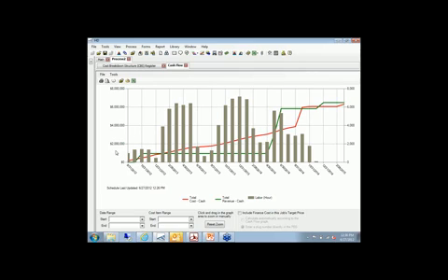And again, this is another thing where if we want to really work on leveling out these resources where we don't spike up and then have these valleys and peaks, right? We can try to level those off. Something obviously Primavera is very good at. Okay, but based on our assumptions in the estimate in terms of what assemblies, what crews, what resources are going to do all of the work, right? We had to do that in order to come up with our cost estimate. Now that Primavera has given us the start and finish dates, we can very easily give you visibility into what that looks like. When are those resources needed, either looking at one project or looking at cross projects.